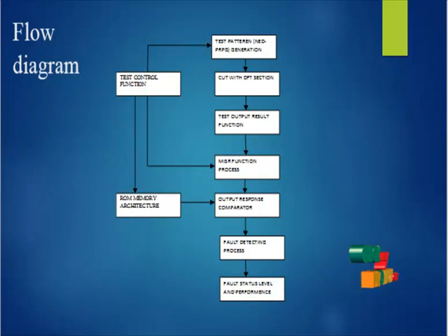This technique obtains the pattern generation based on the test circuit functions. The LFSR consists of D flip-flops connected in cascade with the same clock applied to all the flip-flops to make them act like a shift register. This extra operation introduces a new bit into the shift register.